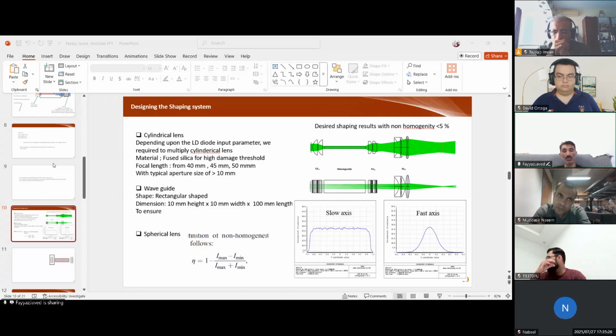To simulate a laser diode source via ZEMAX, the major point is how we input the parameters, because ZEMAX has different parameters. If we select a source diode, you might all be familiar with this window: X position, Y position, tilt about X, tilt about Y, Z, material, layout, and analysis.